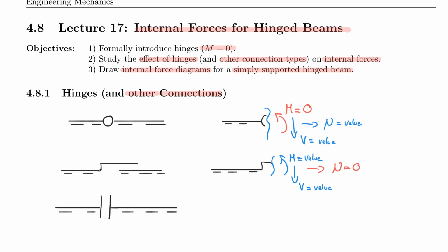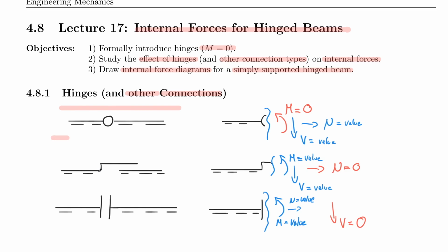And very similar for the shear force connection, which looks a little bit like a battery in electrical engineering, but it's something very different. It's effectively where the shear force goes to zero. I'm cutting right through the middle there, and now I still have my moment and I still have my normal force, but I do not have a shear force anymore. So the shear force would be equal to zero. However, in this class, we mostly focus on the hinge.